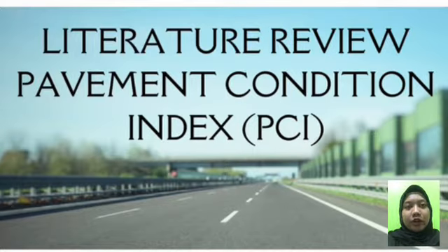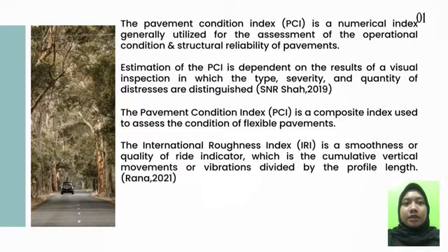Assalamualaikum warahmatullahi wabarakatuh. My name is Nur Hamizah binti Hafiz and my matric number is CF210308. Now I will continue with the literature review of the PCI. PCI is the Pavement Condition Index, a numeric index generally utilized for the assessment of the operational condition and structural reliability of pavement. Estimation of the PCI depends on the result of a visual inspection of the type, severity and quantity of distress. It is a composite index used to assess the condition of flexible pavement.